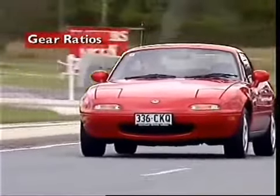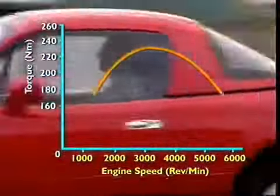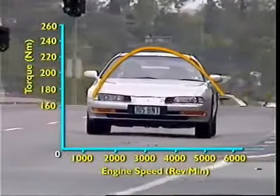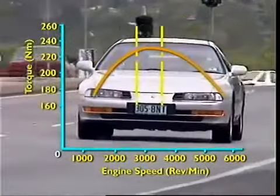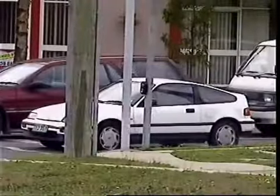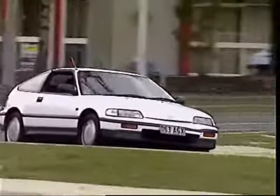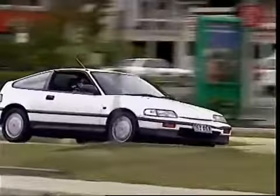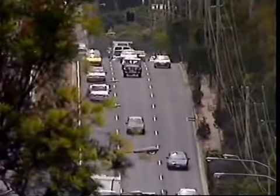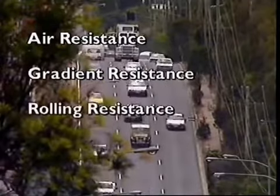In light vehicle applications, the engine operates over a wide speed range, but produces maximum torque only within a relatively narrow RPM band. A relatively large turning effort must be applied to the driving road wheels to move the vehicle. Then the turning effort must vary to overcome air and gradient resistance and rolling resistance.